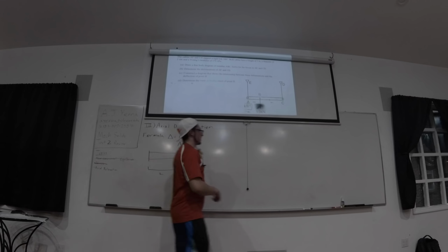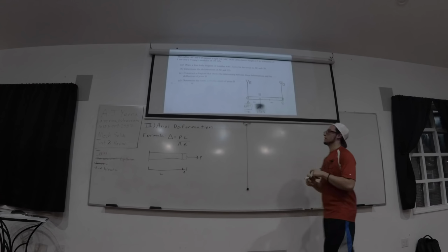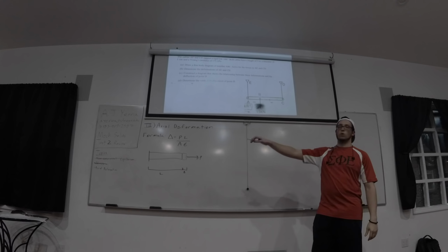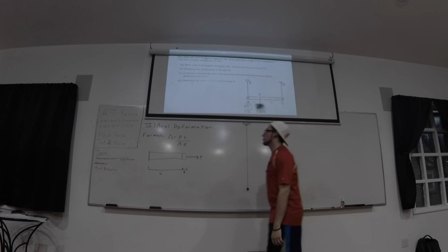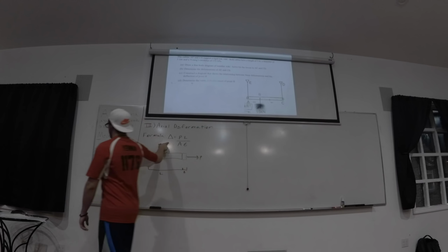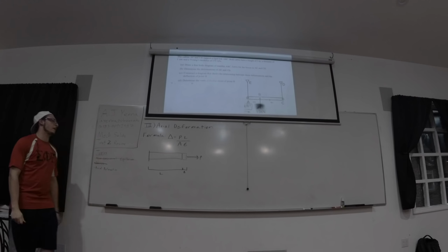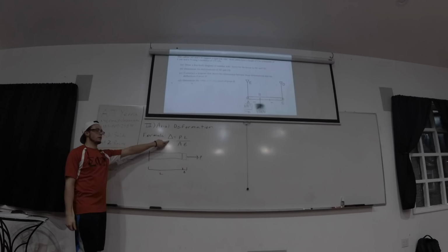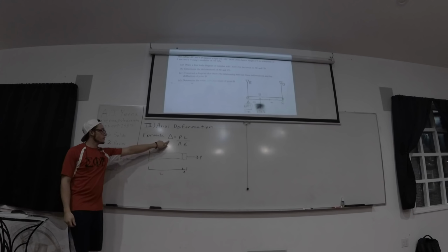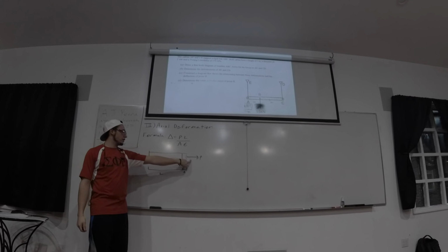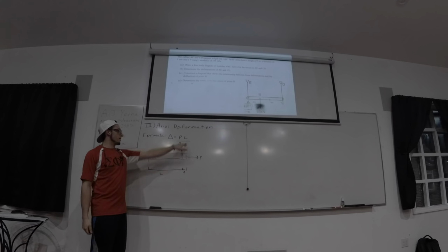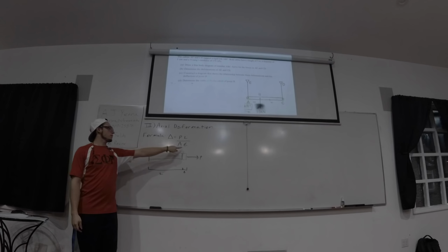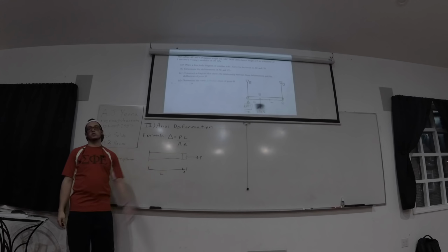So, the last topic that you have to worry about is axial deformation, which actually just turns into a very simple one equation plug and chug. So, the formula is delta equals PL divided by AE, which turns into the deformation in any beam or rod is equal to the force exerted onto that rod times the length divided by the cross-sectional area times E, which is Young's modulus.